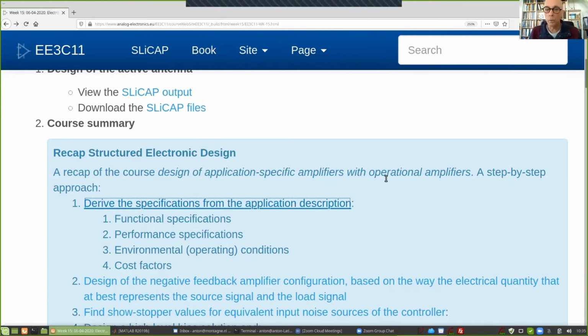Initially, we knew that the open circuit voltage was a measure for the electrical field strength in which we had our information. But since the antenna is linear and very predictable, we can also take the current. At the output of our amplifier, there was a long cable. And this cable should be driven from its characteristic impedance. And in this case, it was specified like 50 ohm.